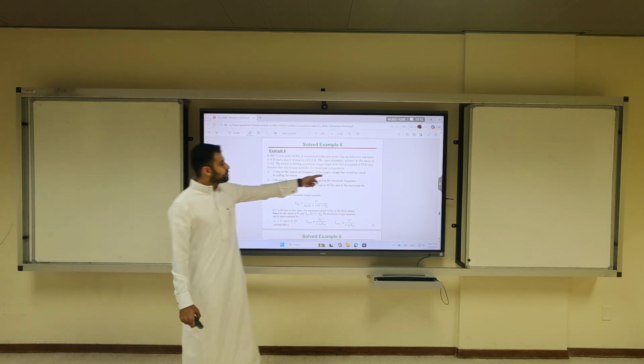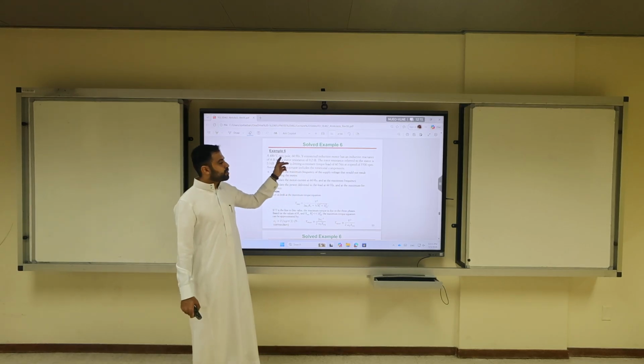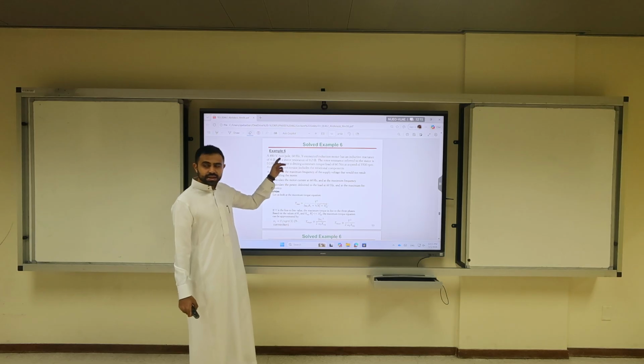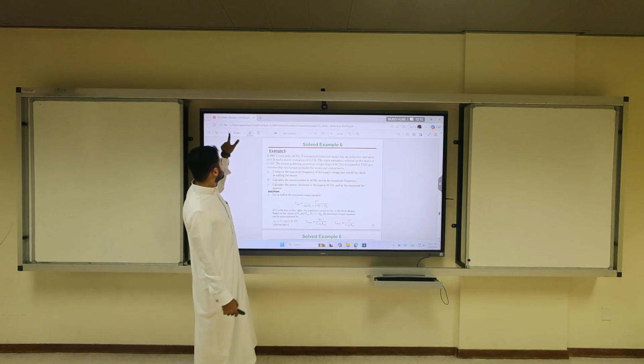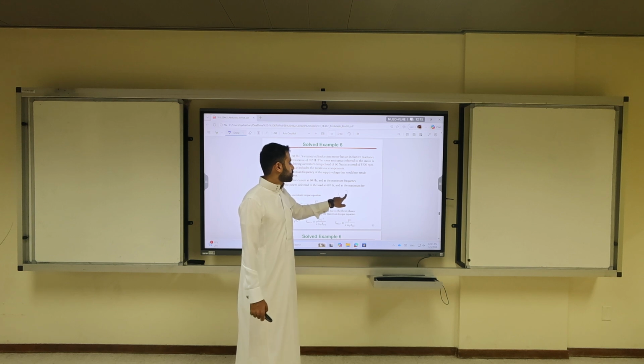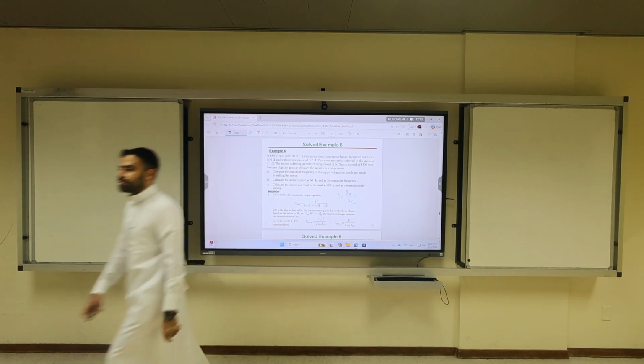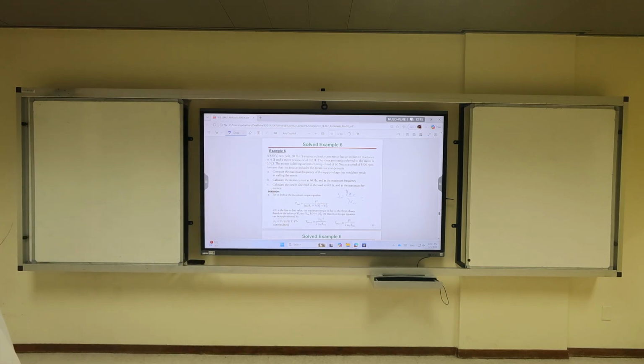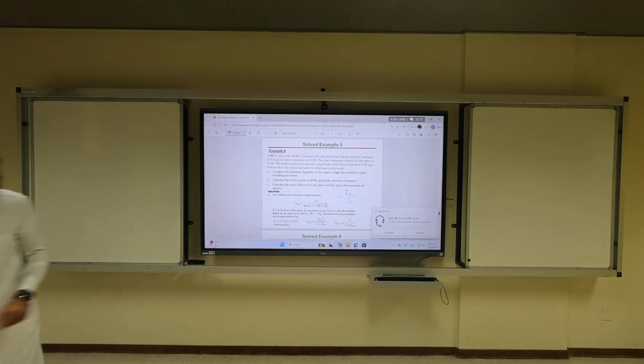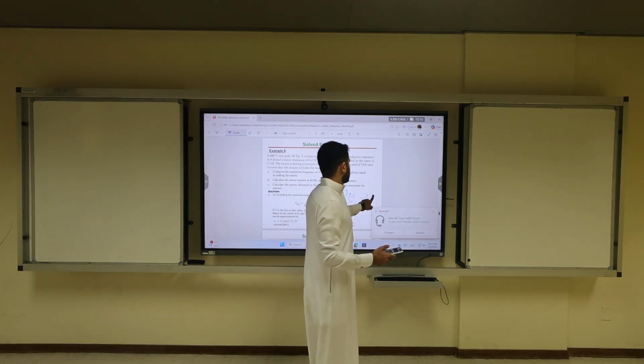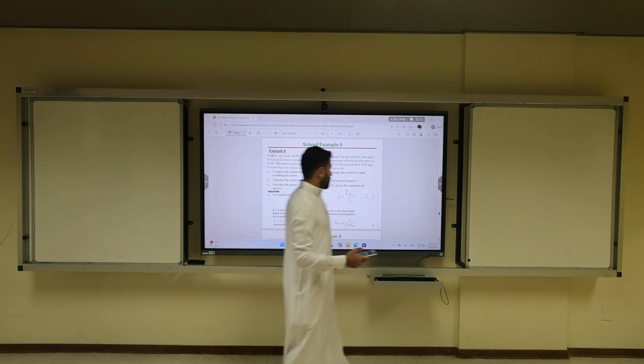What is the synchronous speed? 120 times f over P. No, it's 3600 RPM for a 2-pole machine. So what's the slip? What's the slip? 3600 minus 3500, times 100, over 3600. Okay? So your slip is 2.7, 2.8. Okay? Then what is happening?